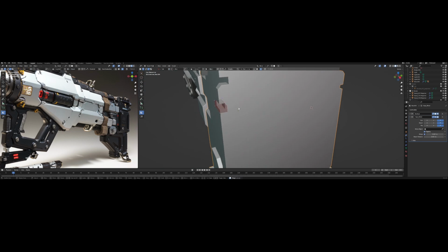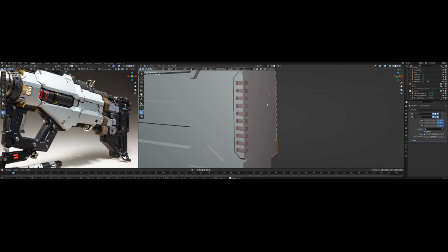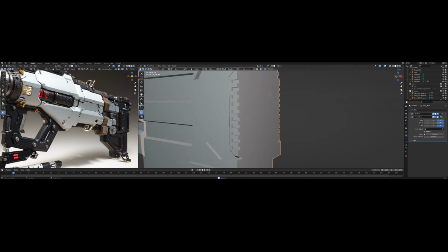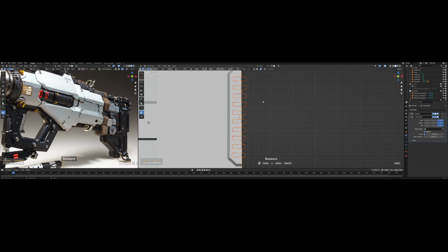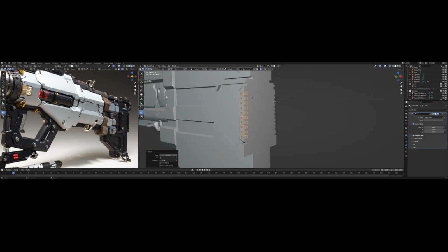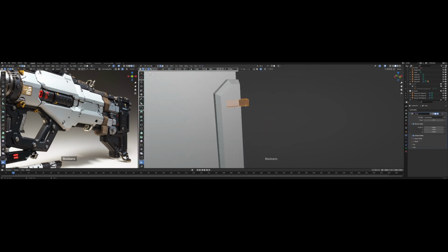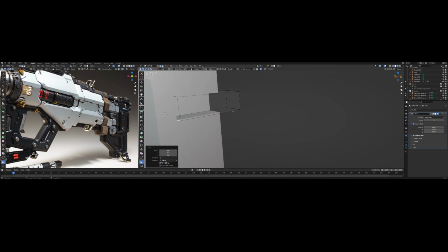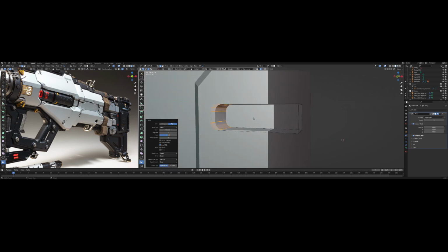And this time I'm still using the box cutter to dig more holes in this part, and I just press V to make an array. Then we can go to the modifier to adjust its angle by pressing Y or Z, so that I will array those Boolean parts along the Z-axis or the Y-axis.